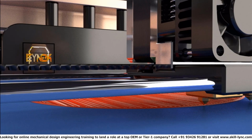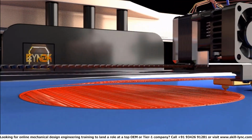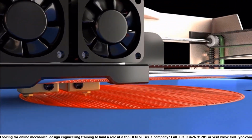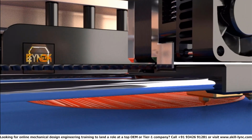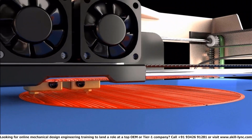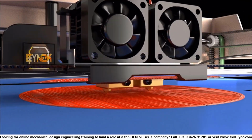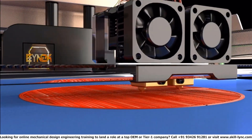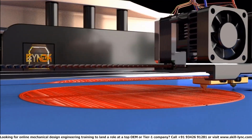So you can print your support structures from this type of filament, and once your print is done, you can submerge your whole model in a tank of water to dissolve away some of those support structures and get a better finish than by manually or physically removing the parts, using a file, sandpaper, pliers, knives, or whatever.